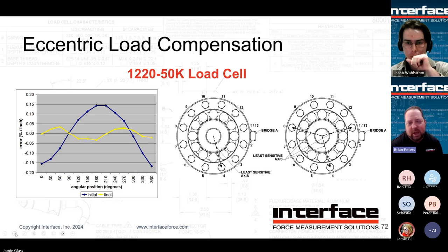So what that means now is this load cell has several neutral axes where it's completely insensitive to off-axis loading, which is pretty significant. So again, this is how you can have confidence that if you use one of these load profiles, you're going to get good results in your test. Even if you have, let's say, a long horizontal load string run, you got actuators hanging off of things. Again, sometimes even with support, you still can't quite neutralize. An LP is not going to care in most cases.